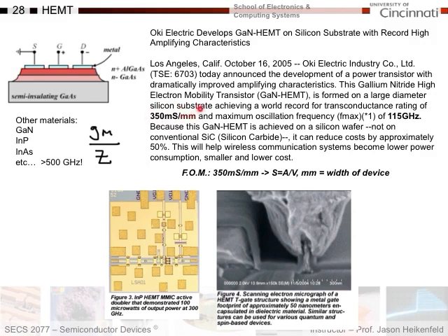So this is the true figure of merit. Maximum frequency 115 gigahertz. Very fast device. To make it fast, look what they've done here. This is the gate, and there's the gate contact there. What have they done here? You can see that they're going through huge efforts to make the gate as small as possible.